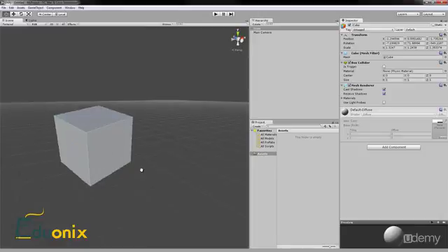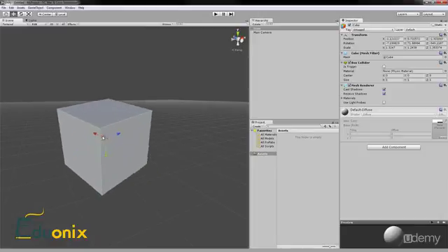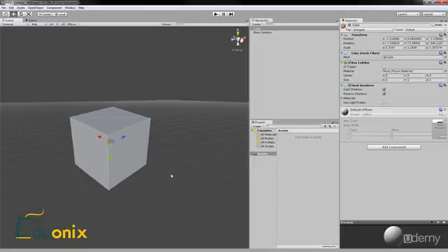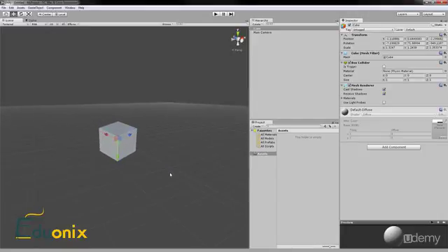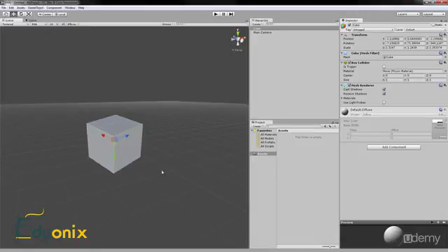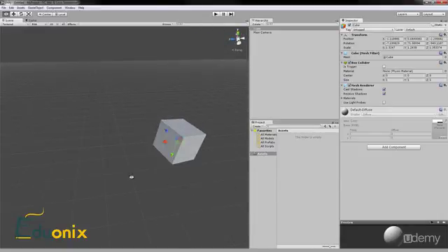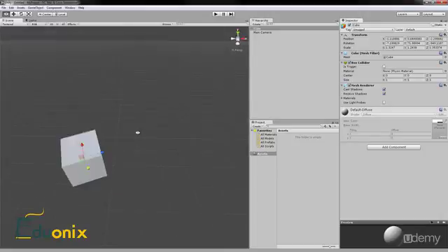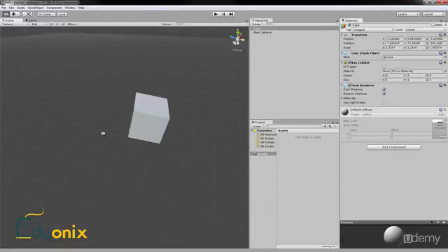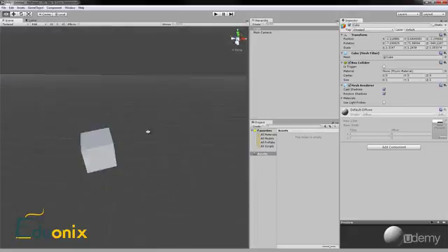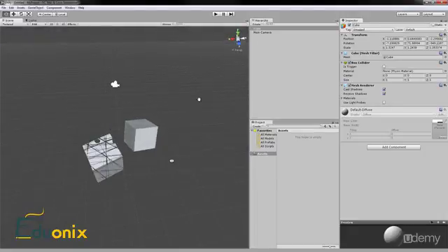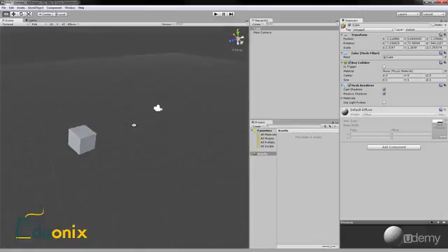Now, additionally, if you're using the translate tool and you don't want to press Q, if you hold Control, actually Control doesn't do anything. Anyway, if you want to move around, you can click Alt, and then click and drag, and this will allow you to rotate the scene camera. This is very helpful. So, alternating between Alt and Q, I'm able to move the scene camera to any position I want and kind of give myself a better view of this cube.